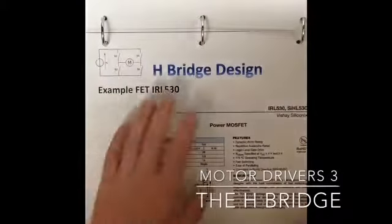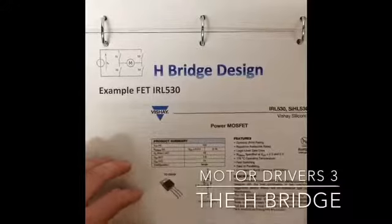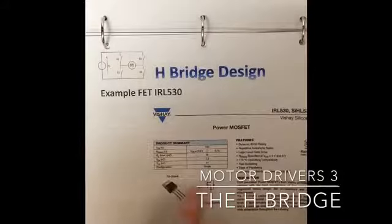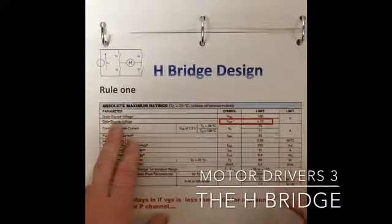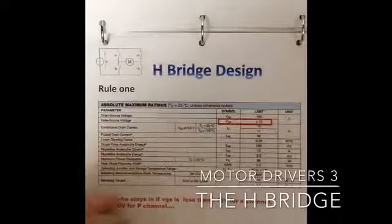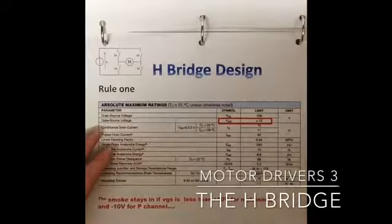If we take an example of an IRL530, a typical guy, you can see here that his VDS max is 100 volts. He has a specific pattern. It's an N-channel MOSFET. The key thing is when you look at the gate to source voltage, the limit is plus or minus 10 volts. So if I put more than 10 volts from the gate to the source, I will cause problems with this FET. The smoke will stay in if VGS is less than plus 10 volts for an N channel, minus 10 for a P channel.